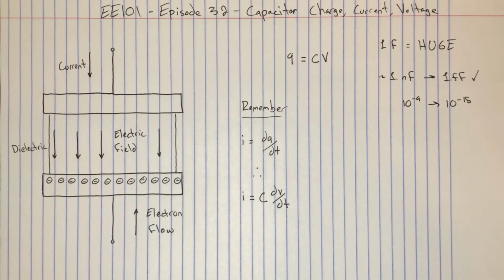And this is a pretty crazy result. The intuition we gain from this derivative relationship is that current will only flow through a capacitor if its voltage is changing. Essentially, if you try to apply DC voltages and currents, capacitors look like open circuits. And I encourage you to think about the implications of that for a second. It means we only care to think about capacitors if our circuits involve AC signals. As far as a DC circuit is concerned, capacitors may as well not even exist.